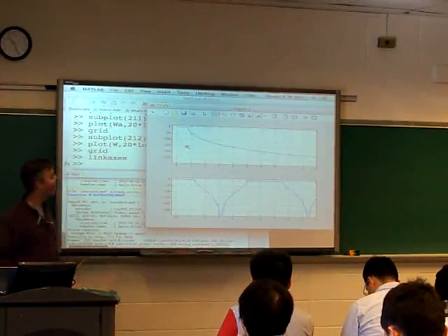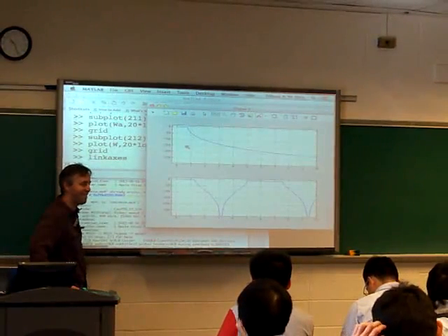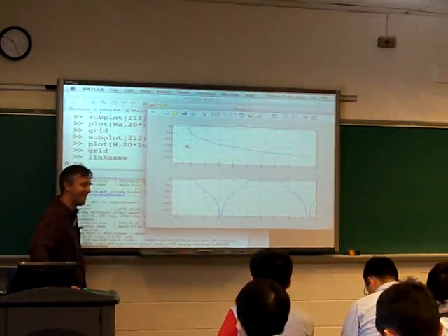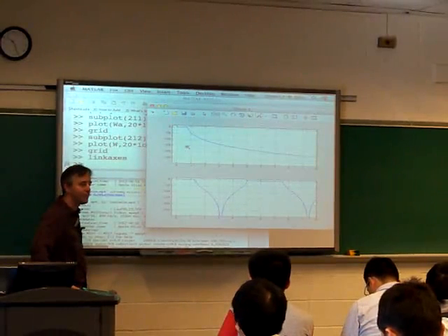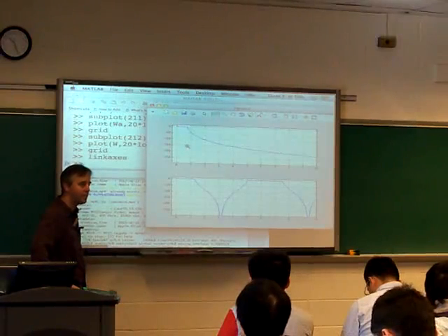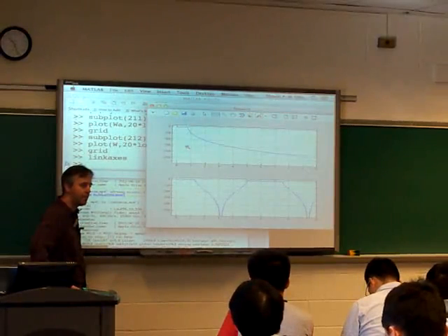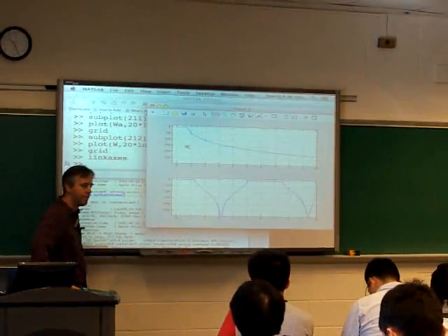But so, yeah. Ideally, we want a filter which would attenuate a frequency not in the band of interest. Like say if I want specific attenuation at a frequency, say at 3 pi by 4, 3 pi by 2. Yeah. I'm not getting that attenuation here because of this aliasing happening.